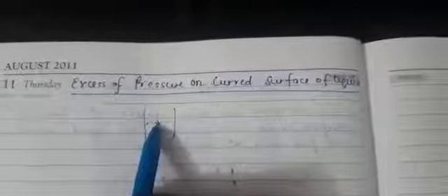And force of surface tension also acts tangential to the liquid surface at rest. Now the direction of the resultant force on the molecule basically depends upon the shape of the liquid meniscus. So what can be the shape of the liquid meniscus? It can be plane, it can be concave upward, it can be convex upward. So we can treat it that the liquid meniscus can be plane or it can be curved. Now if the liquid surface is plane, we have to just learn the result on this basis.